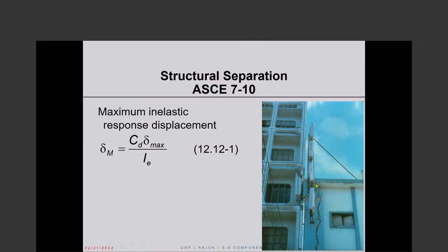Okay, I think I have shown you this picture from the Mexico earthquake 1985, and the point of the picture, and this is always true in this business of hammering, the most important thing is whether the floor levels of the neighboring buildings align or they don't. In this picture, they are not aligned. So the heavy floors of the right building hit against not quite mid-height, but along the height of the column of the next building, and a few poundings like that, the column gets damaged, and then a whole portion of the building can come down. Okay, if the floors are aligned, the damage is significantly less, but we cannot regulate by building code that floor levels of neighboring buildings shall be aligned. That is pretty absurd. So this is why we go to this avoiding damaging contact.